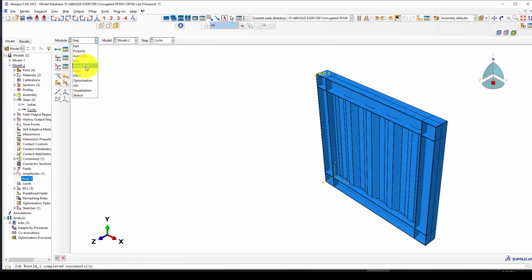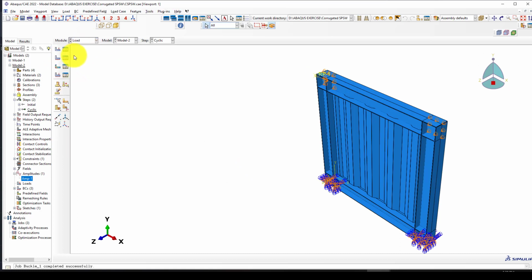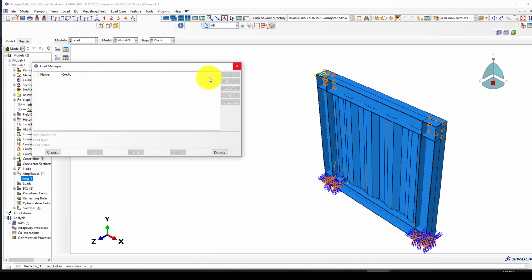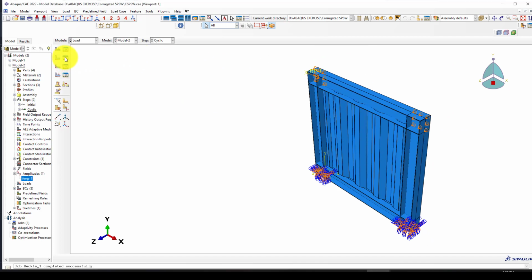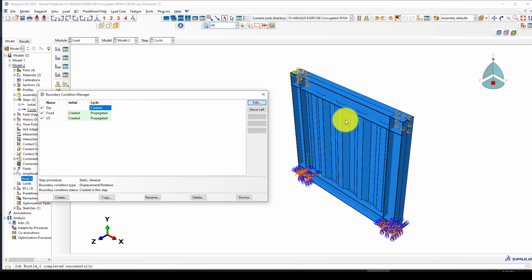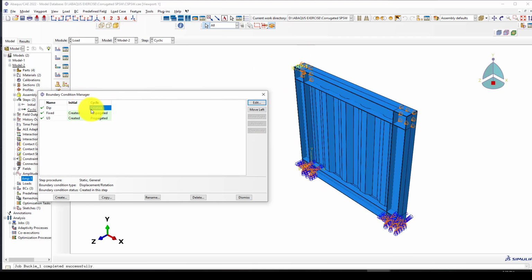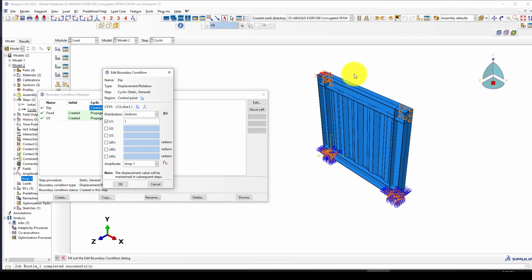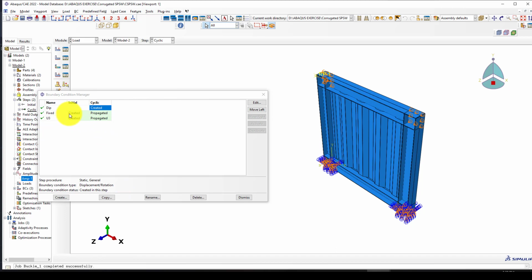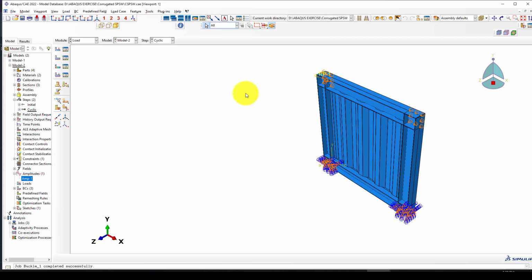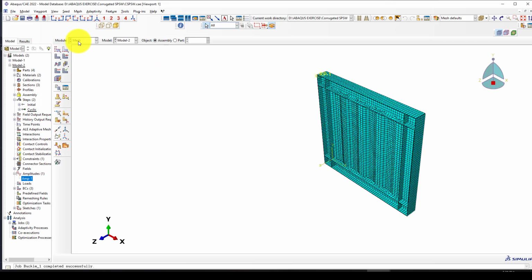Now we finished here, we go to the interaction. The same, we need one interaction and also a load. In the load we can consider some gravity load in case you have, but I suppose I don't have it here. And now here is the displacement. In the previous step we called buckling load, so now we want to create a displacement using one unit in this direction and using this amplitude which is previously defined, and the same others from the previous initial step, fixed and U3. So the mesh is also the same mesh.